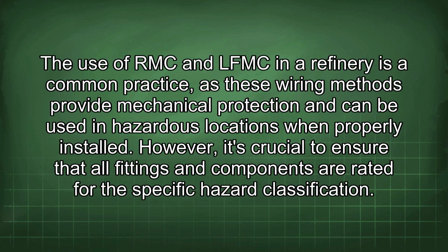The use of RMC and LFMC in a refinery is a common practice, as these wiring methods provide mechanical protection and can be used in hazardous locations when properly installed.